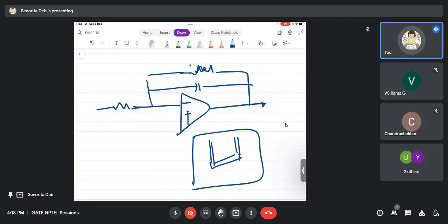Okay, and those noises will then cause your op-amp output to be unstable. So therefore we add these kind of additional capacitors, which are very small value capacitors. So this is 0.1 nano, right? So very small value capacitors are added so that those high frequency oscillations are grounded.